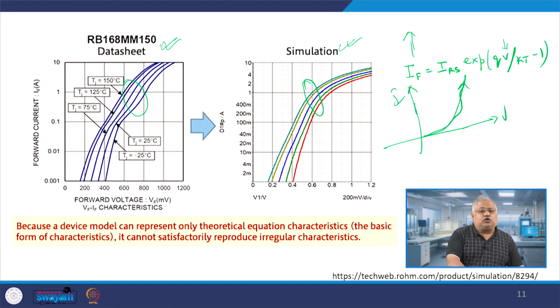And finally, we saw that if your device output characteristics, experimentally determined, are highly irregular in nature, no mathematical tool will be able to emulate them 100% accurately. So, we forego that small amount of error and we say that our output characteristics is fast in terms of fast convergence rates, right. So, this was what we have discussed in the SPICE simulation, at least in this case.